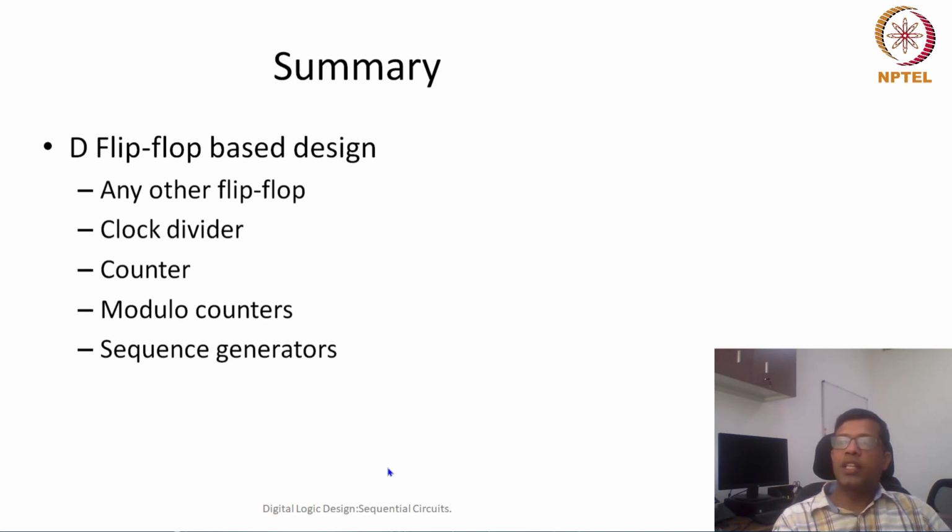That is how we can design synchronous counters. And using the similar technique, we can also design modulo counters. We can also design any kind of sequence generator where the sequence is some integer numbers, and from one integer number we would like to go to another integer number. That kind of sequence generator can be designed using D flip-flops.